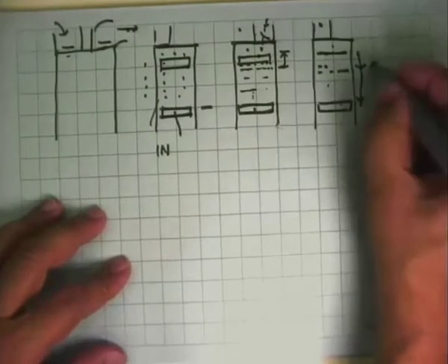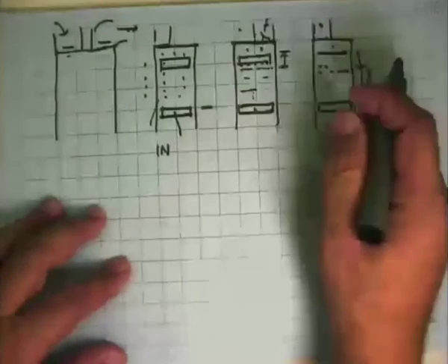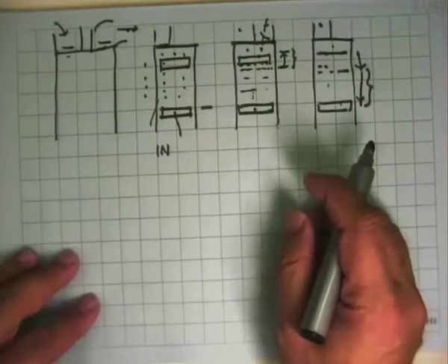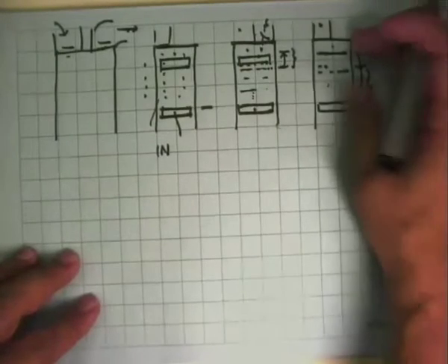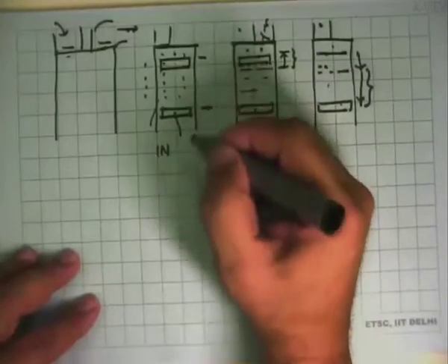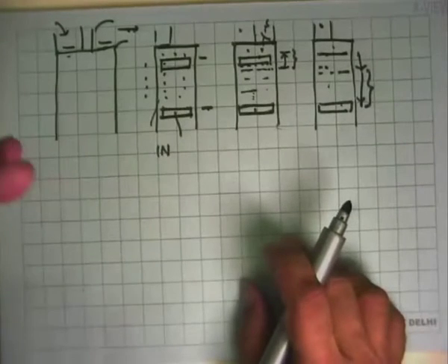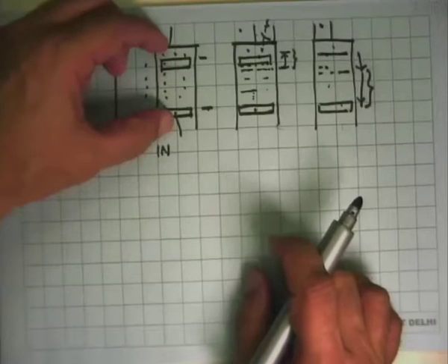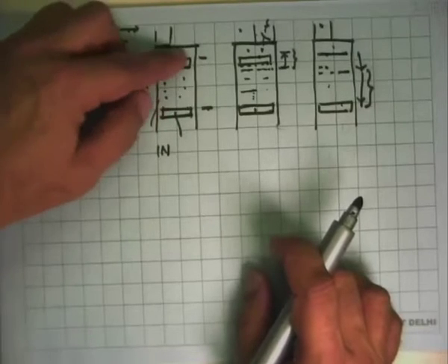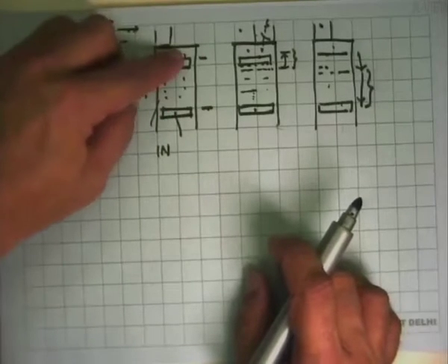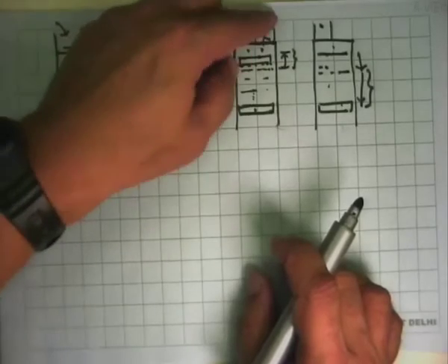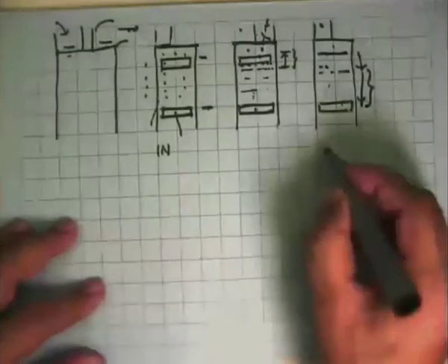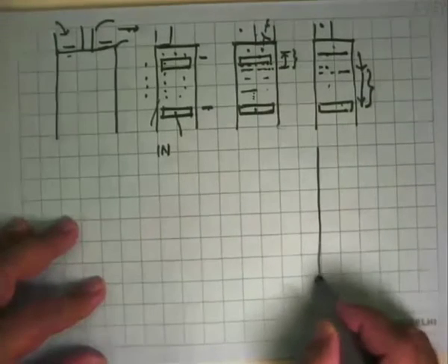So there is this travel when it takes in air, and this part when it pushes it out. So even though the total displacement from top to bottom is this much, the actual amount of vapor that is taken in is less than this total volume, because there was some dead volume here already which was always going to be there, and only a certain volume is what went out. So if you draw it on the pressure volume diagram, here is what we get.